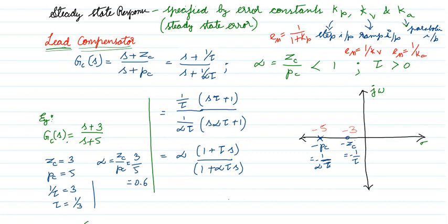All of these forms are the same, just a different way of representing. That is the point you have to remember. All are the same lead compensator. The only condition is the zero should be close to the imaginary axis. I have given an example, right? And one more thing, this alpha, that is your ZC by PC, should always be less than 1. You should keep that in mind.